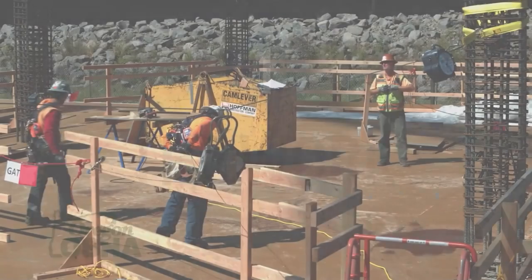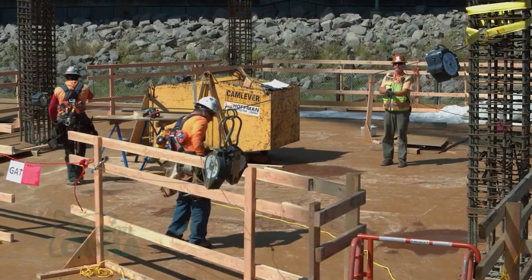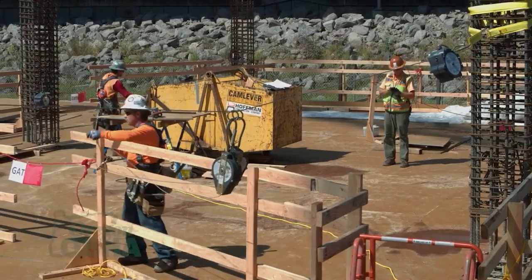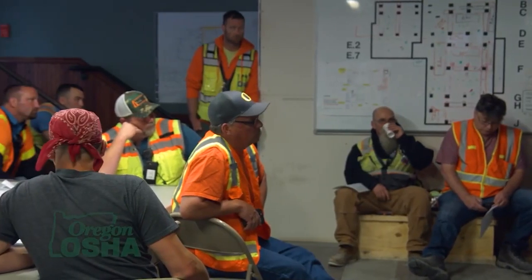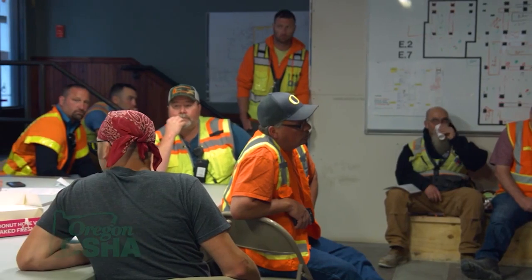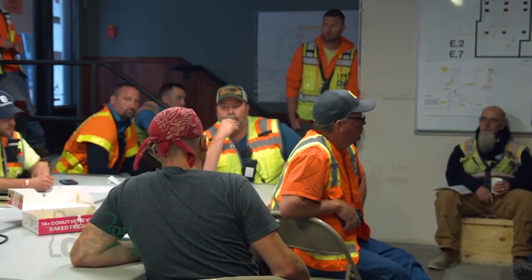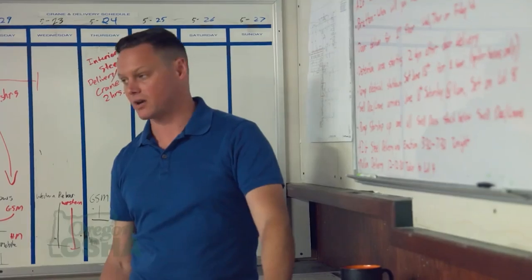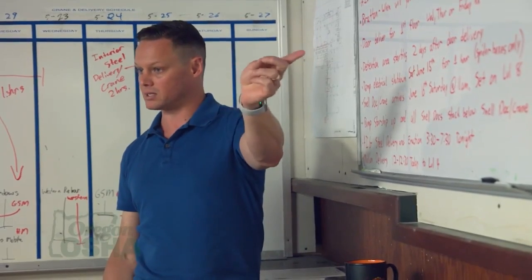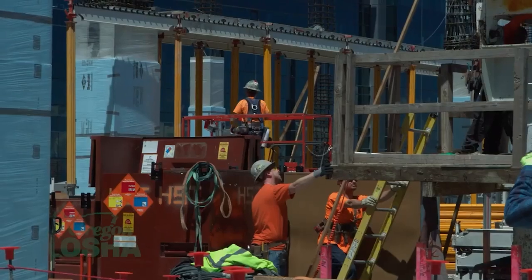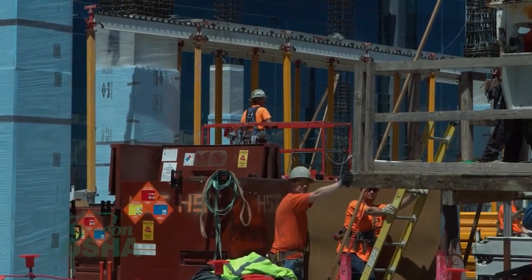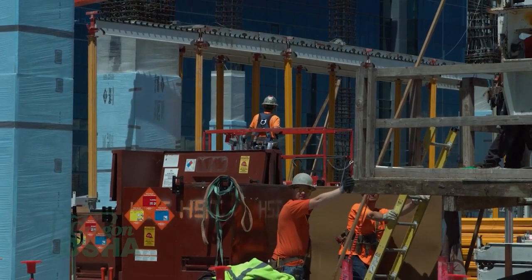I usually identify high-risk activities, and then at that time I work through the plan with the team that's going to be doing it, or at least the foreman and superintendent that's going to be performing that work. And I like to have them tell me the plan, and then I also know how that work's going to go, and then we identify certain areas where we can eliminate risk, and then we try to have a plan before we even get started to eliminate that.